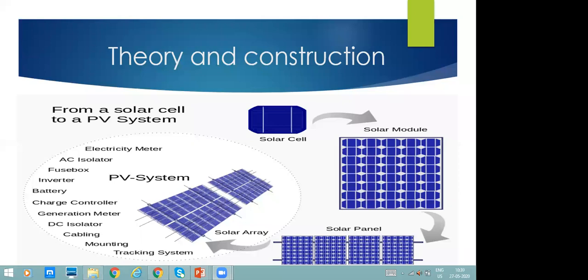And PV junction box, PV is photovoltaic. A photovoltaic junction box is attached to the back of a solar panel and functions as its output interface. External connection for most photovoltaic modules use MC4 connectors to facilitate easy waterproof connection to the rest of the system. A USB power interface can also be used.